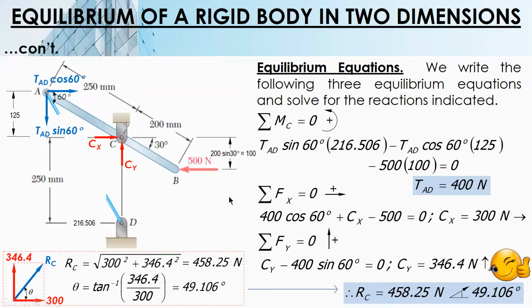Okay, so again, as a summary of the steps you need to take, if there are inclined forces, you have to resolve it into x and y components before you apply the three conditions. And first, consider summation of moment, because if you sum up forces along x and y, we have two unknowns. So you go directly to summation of moment to avoid repeating the equation. Para diretso.